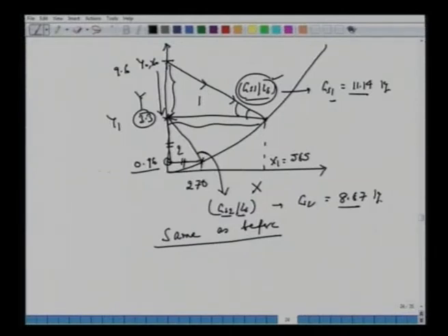We can get this number here, which is y2 equal to 0.96. So whenever we have this question of phrasing the problem, one has to be careful, both mathematically and analytically. There will be iterations if stages are given and the amount of solid is asked to be determined here.